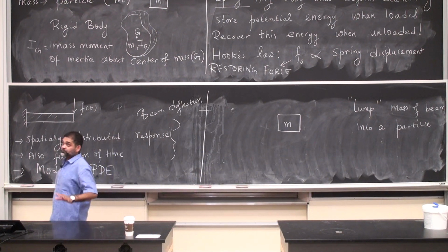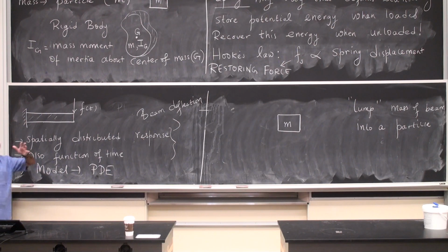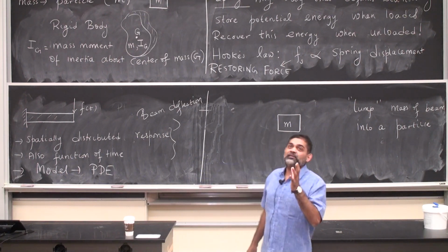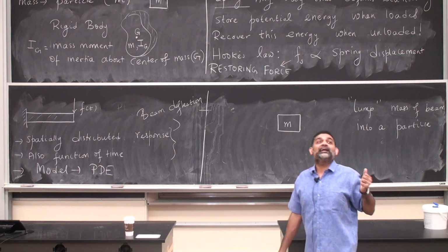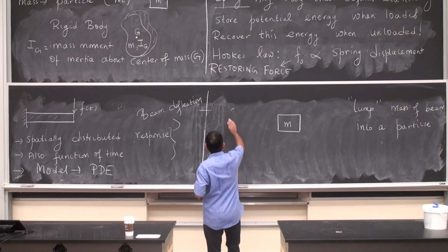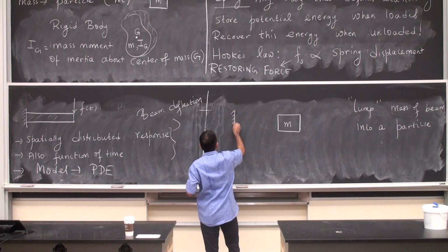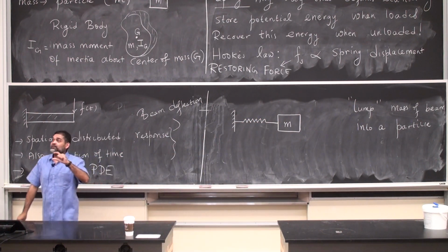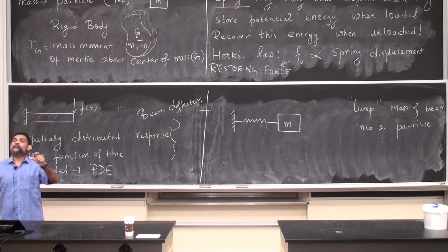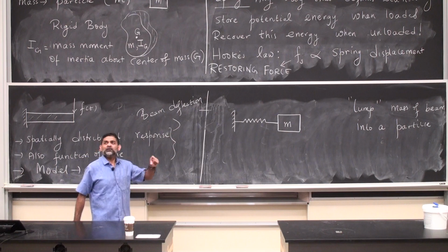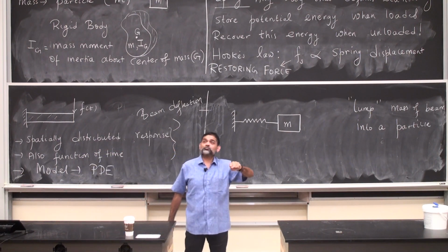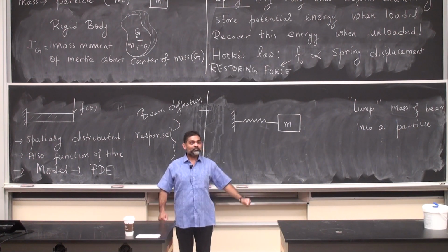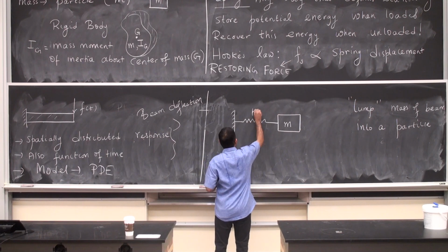Then what we say is, okay, as I apply a force to this cantilevered beam, what does the beam do? The beam undergoes an elastic deformation. This elastic deformation of the beam can be characterized by drawing a spring element, okay? A translational spring in this case. The stiffness of the spring will tell me the nature of the stiffness of the beam itself. Is it a really rigid beam where I have to apply a large force, or is it like a springboard in your swimming pool where the force applied is not really that large and I can see more of a deflection of the beam? Okay, so this is the stiffness of the beam.